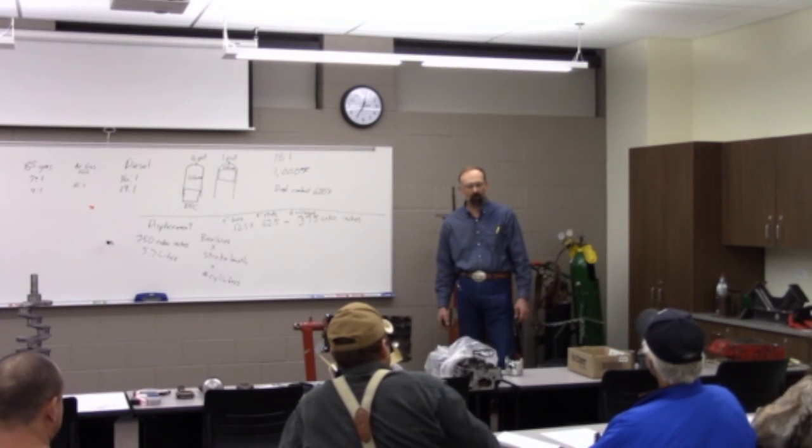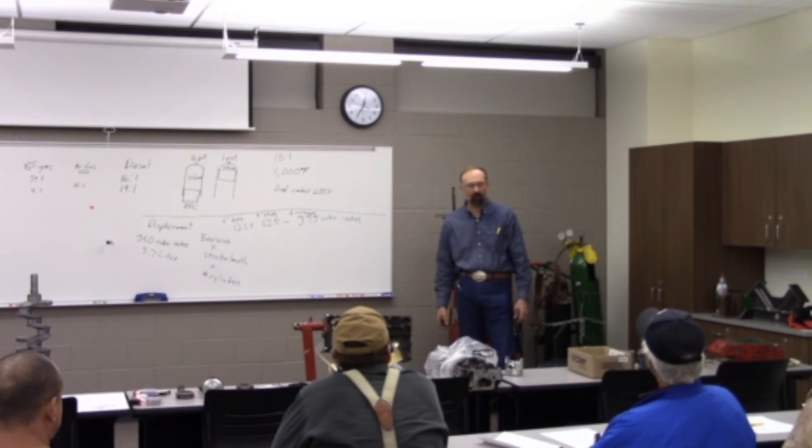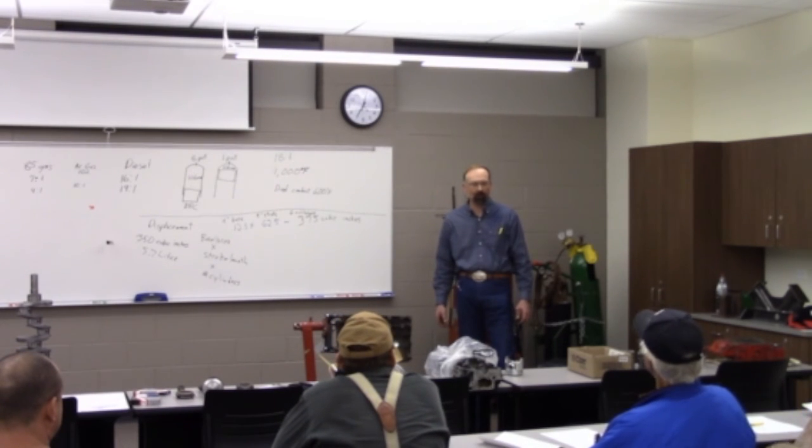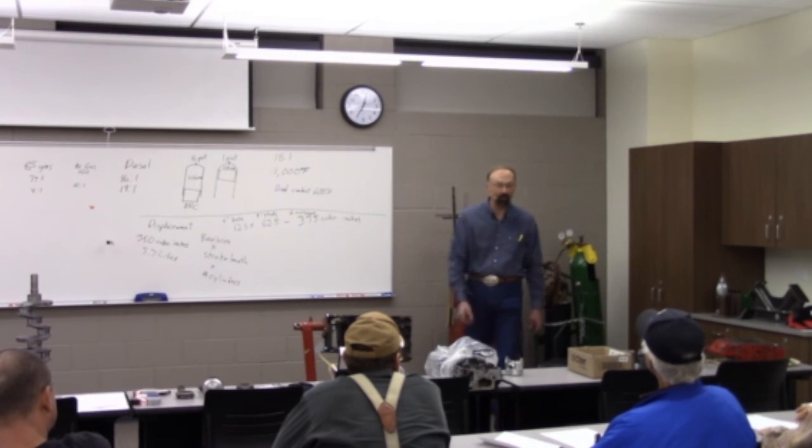And I know there's some engine designs that you'd start seeing some of that by the time you got to 30 thousandths over, and there were others you could go to 60 thousandths over and not have that problem. But on a lot of engines, 60 thousandths is typically the maximum that they make any oversized parts for. But there's a lot of engine designs that don't even go that far, and maybe that problem is why.